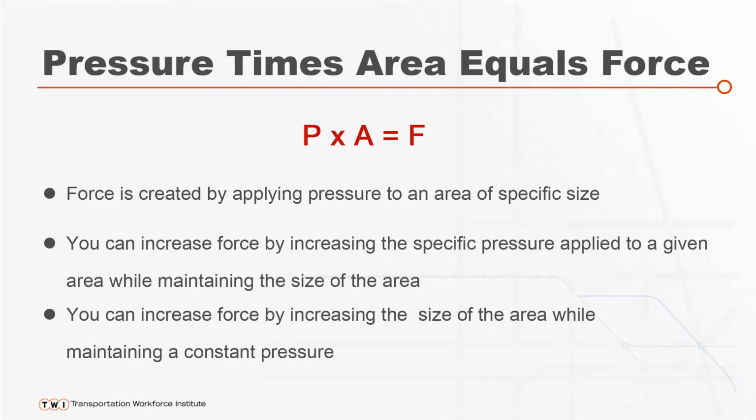Now, in the braking system, it's important to understand that the pressure is varied by application valve pressure. Most brake applications take place between 10 and 20 psi of pressure. 10 pounds of pressure multiplied times 30 square inches is going to give you 300 pounds of force, and conversely, 20 pounds times 30 square inches is going to give you 600 pounds of force. So most brake applications take place at low pressure.